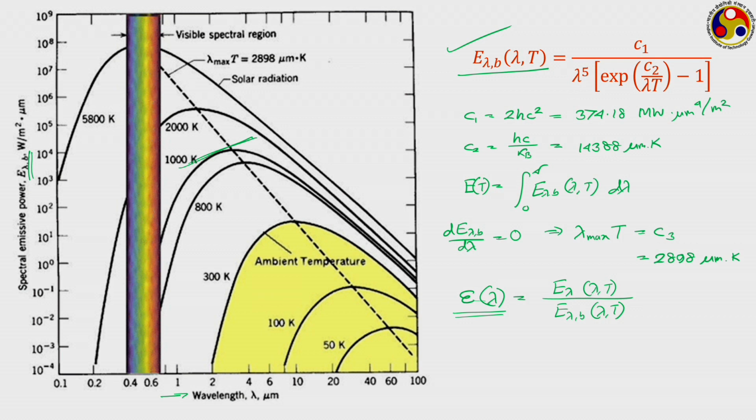Now, the principle is that whenever a surface is emitting certain radiation, we shall be using some kind of detector which is going to sense that radiation. Energy is coming to this particular sensor in the form of radiation, accordingly its temperature increases, but it will also lose energy to the surrounding in the form of its own emission, and there may be convection from the surrounding air if there is anything at all. If there is no convection or conduction heat losses, then it will keep on emitting depending on its own temperature.